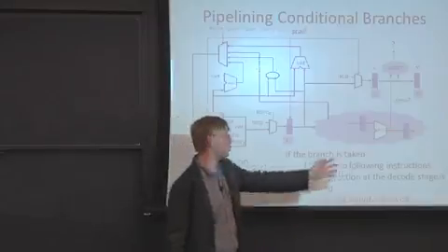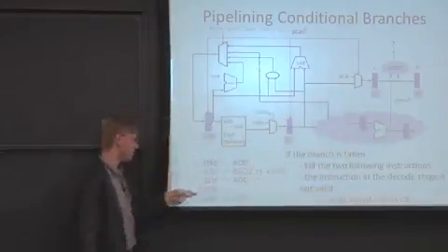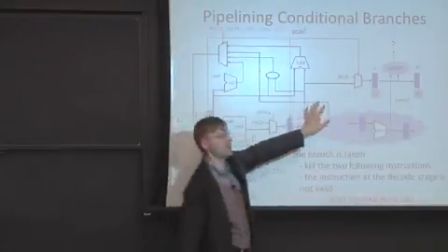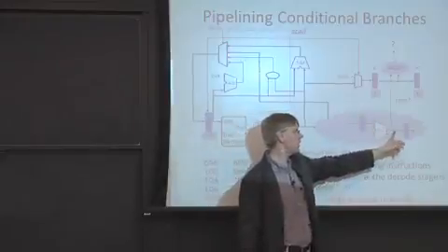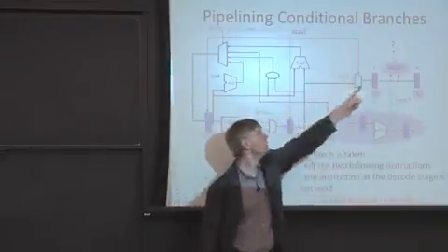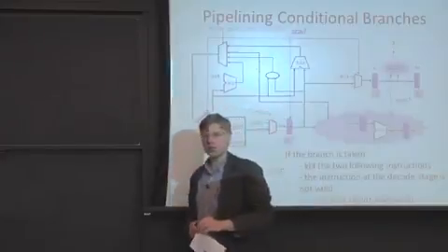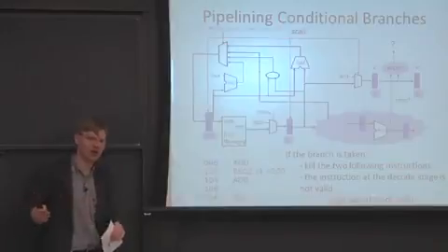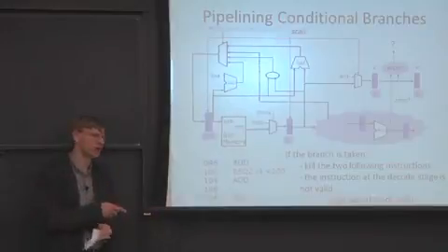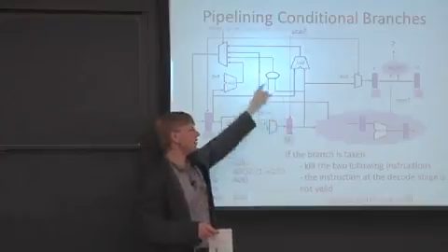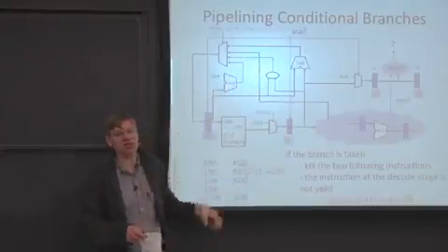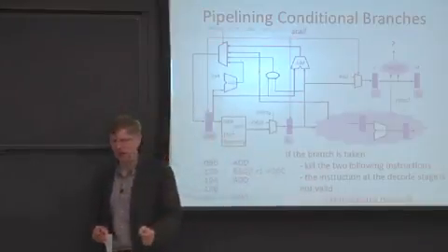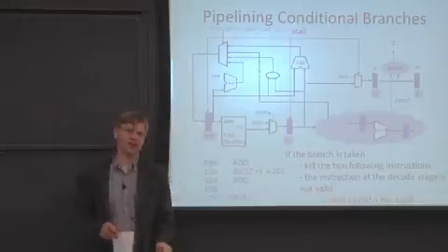And you have a branch which is branching to someplace else. So let's take this instruction here, 104, which is an add, is dependent on something that's stalling the front of the pipe. But at the same time, you want to kill because you took the branch. You want to kill that instruction. If you were to put the stall at the higher priority, you would actually end up with a deadlock because you'd be stalling, but you would have no way of killing the previous instructions to clear the stall. So this is why it's really important that the instruction at the decode stage is now invalid.